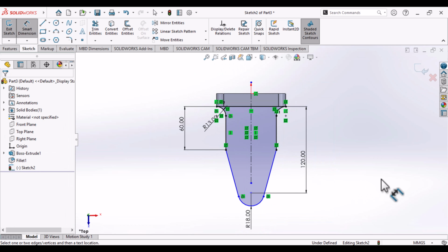All right. Now we can create the circles. The good thing about SolidWorks, why it's more convenient for beginners than CATIA, is I can create all the elements here and then use them separately when creating features, which is different when you're in CATIA.